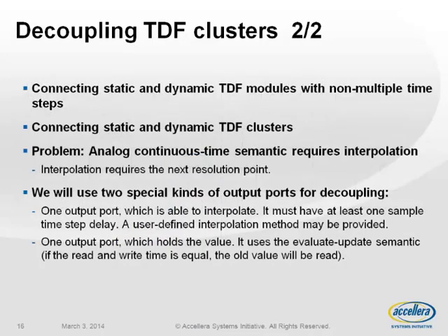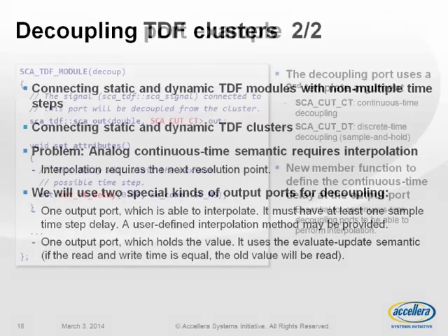These decoupling ports enable you to connect static and dynamic TDF modules with each other, which use different time steps. We have to be able to do interpolation or do a sample and hold mechanism. If we do interpolation, we always need 2 samples to be able to interpolate. And therefore, you will be obliged to assign a certain delay to your output so that the port can accumulate enough state to be able to do this operation.